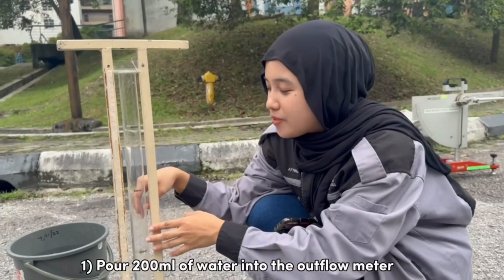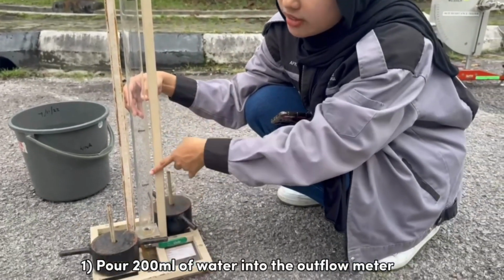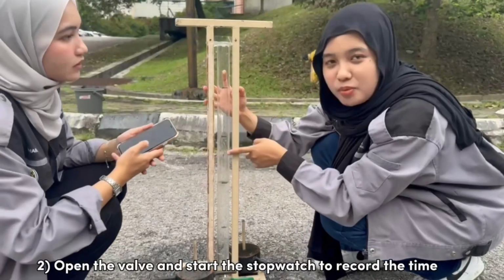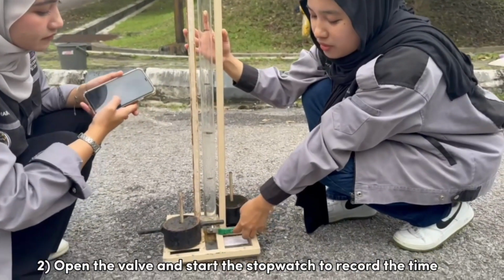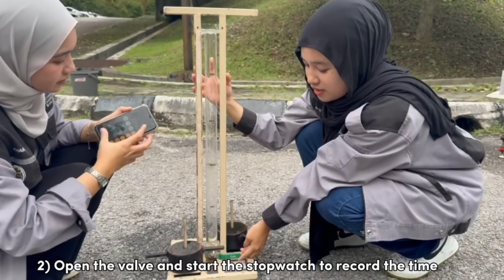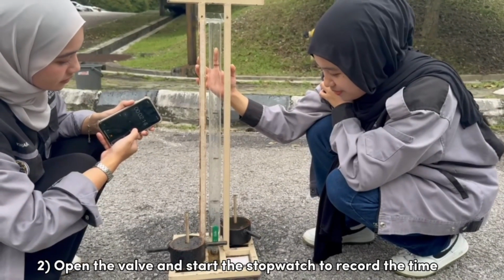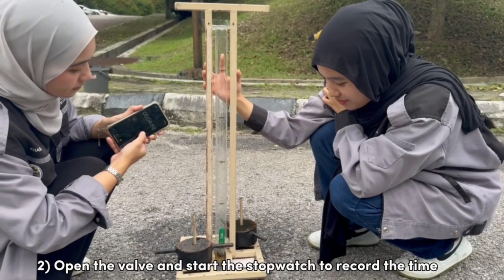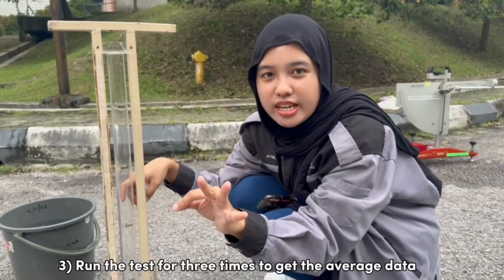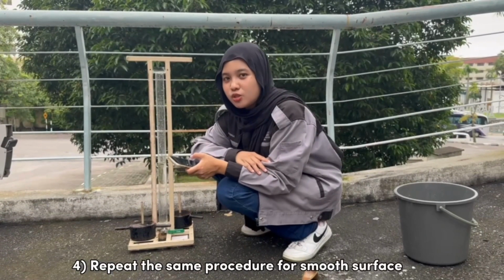Okay, so the first step, we pour the water into the overflow meter until it reaches 200 ml. After pouring the water, we open the valve and record the time using the stopwatch. We need 3 readings to get an average. So we repeat the same procedure on the smooth surface.